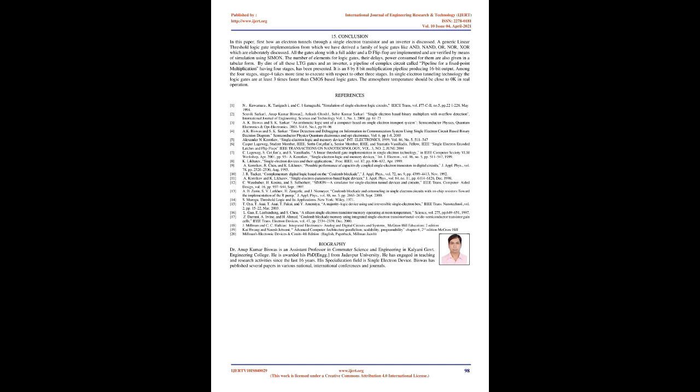By dint of all these LTG gates and an inverter, a pipeline of a complex circuit, called a pipeline for a fixed point multiplication having 4 stages, has been presented. It is an 8 by 8-bit multiplication pipeline producing 16-bit output. Among the 4 stages, stage 4 takes more time to execute with respect to the other 3 stages. In single electron tunneling technology the logic gates are at least 3 times faster than CMOS-based logic gates. The atmosphere temperature should be close to 0 K in real operation.